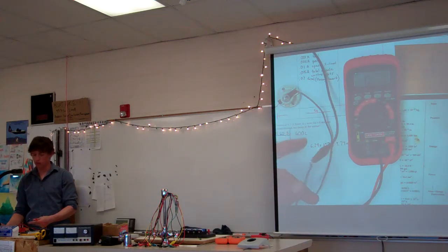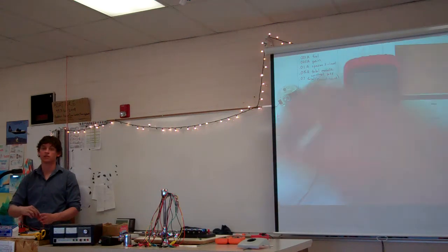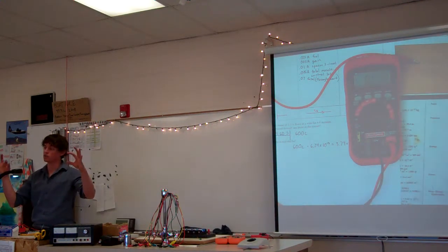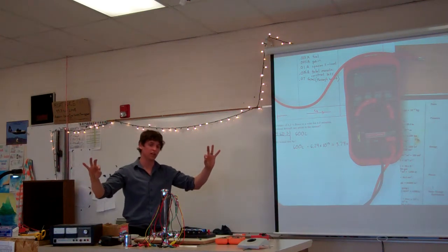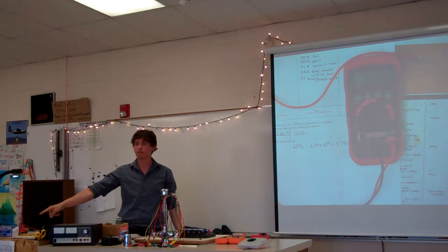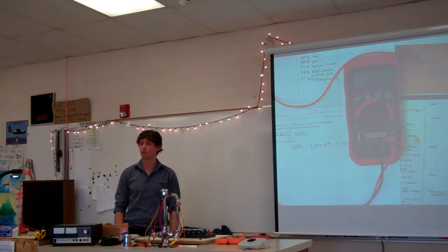Okay? So when you take your car in to the mechanic and there's an electrical problem, they often use an ohm meter to tell what the problem is. Because if they connect to a certain circuit, say your window motor, this side of your window motor and this side of your window motor, okay, the wires, they connect and it says that means that little unit is burned out. Okay? If they turn the switch on and it doesn't read a resistance, they know that thing is fried. They're going to have to replace it.